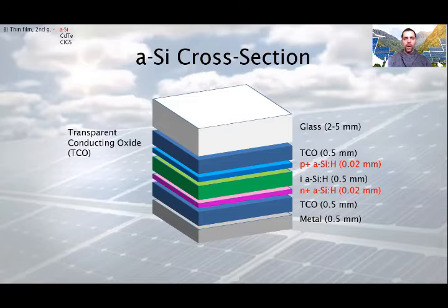These products require higher currents than small cells, and it was found that an additional layer called a transparent conductive oxide, TCO, could facilitate the movement of current across the top of the cells instead of a metal grid. One such TCO, tin oxide, was available for other uses, for example, thermally reflective windows. Made more conductive for PV, tin oxide became and remains the norm in cadmium telluride photovoltaic modules.